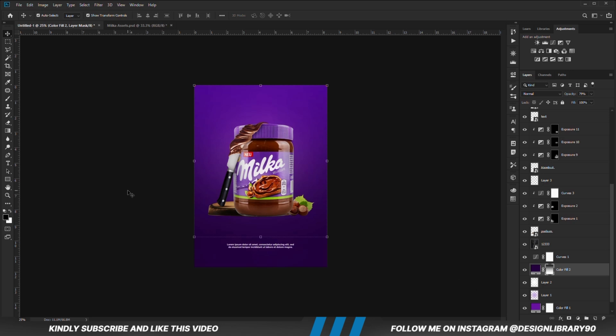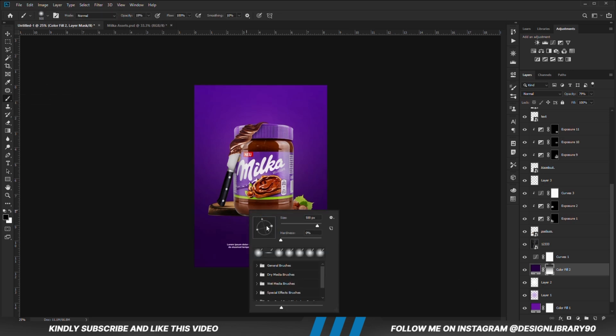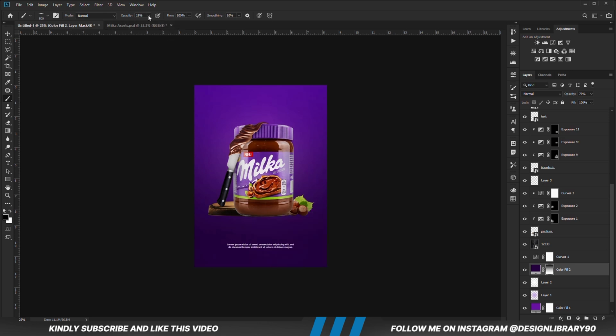With the mask still selected, we grab a soft hand brush. Right click and change roundness. Reduce the opacity, foreground is set to black. Then you are just going to make a few clicks to erase that portion.